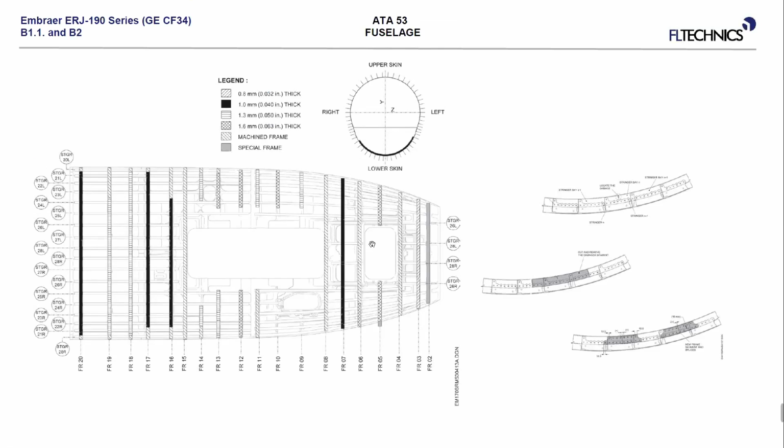Fuselage frame repairs. Again, if your damage is not in the limits, and I told you at the beginning of this chapter, damage on the frames and damage on the stringers is usually not acceptable. Almost all the times it's related with some replacement or at least some repair. That's why you have to be really careful.